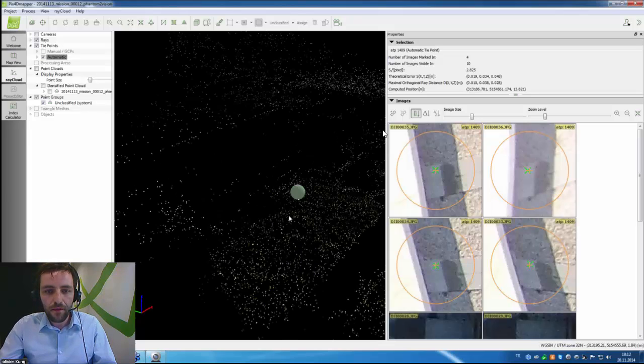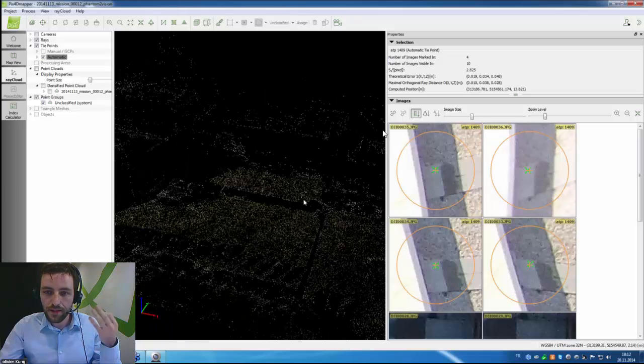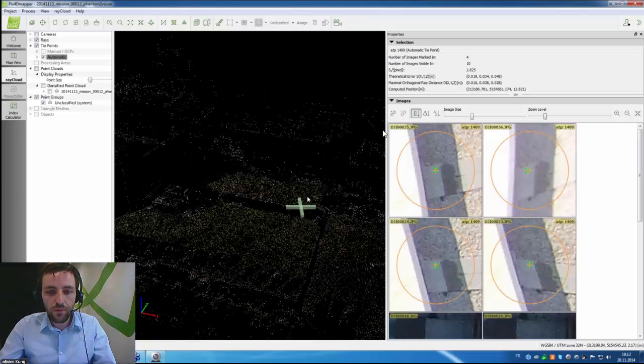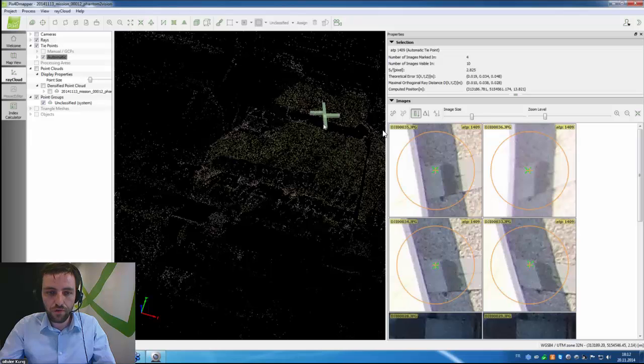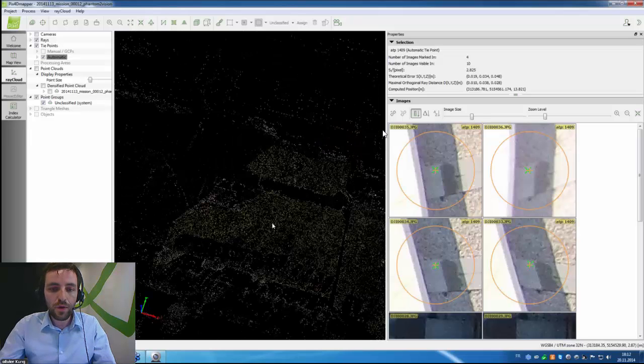Ground control points, the ones that have coordinates, I don't think it's worth adding them on the facade of the building. They will mostly be helpful for improving the geolocation of the project, not of the individual parts of the project.